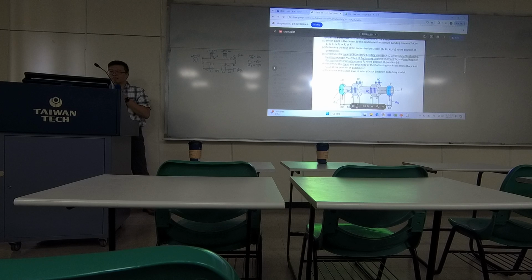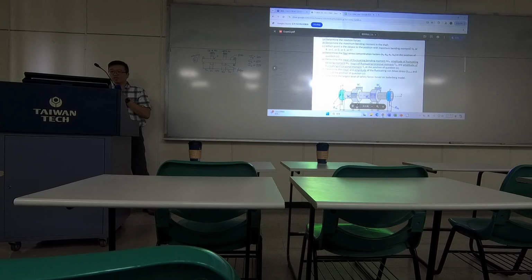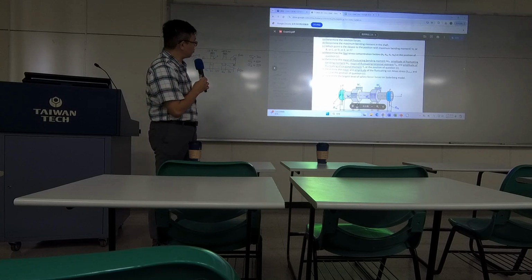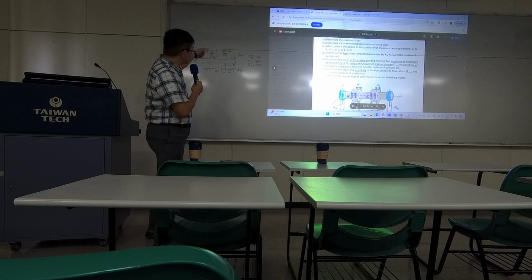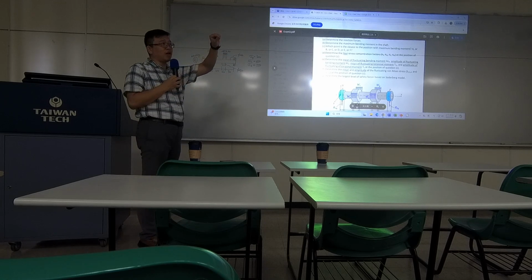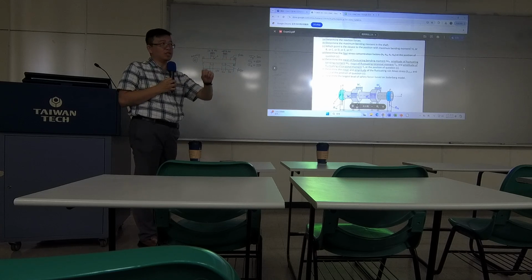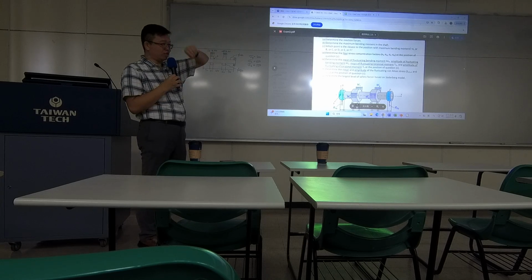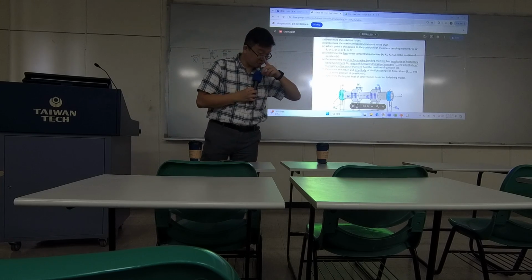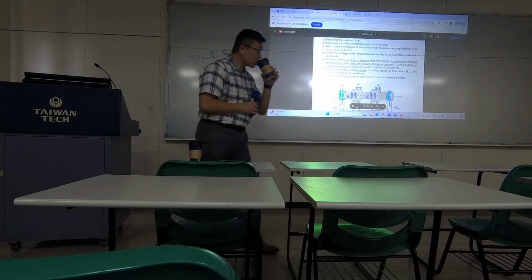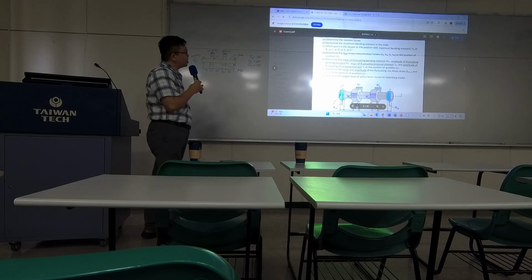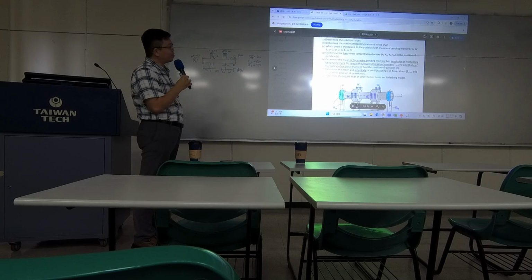Yesterday, some students asked how you determine the fluctuating condition for this, because this is rotating. So if you pick an element on the shaft, it will be experiencing tension and compression along the cycle. So that's how you can analyze the fluctuating level.